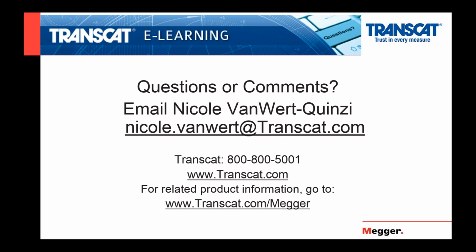What is meant by a capacity test showing over 100% capacity during a discharge test? That can happen because the batteries are rated for, again, 8-hour rated capacity. So you can get, for a period of time, over 100% capacity out of a battery. It won't last, but you can for a period of time on new batteries. Now, keep in mind, when you first get a battery, typically those batteries are what's called green batteries. So when you first test them, they haven't completed their formation.